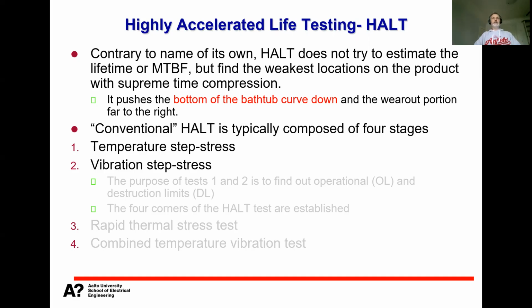So with HALT testing, we do not try to estimate the lifetime or wear out phase, and we do not try to estimate, let's say, the mean time between failures or mean time to failure. So we don't want any numbers, but we want to find the weakest locations, weakest links in the product as fast as possible. So with supreme time compression.